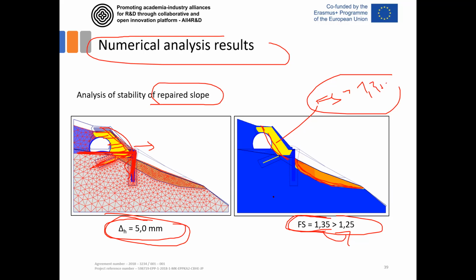As you can see, in this calculation, an additional conservative measure was to remove all this material here. That's actually a possible scenario in the real world, since the stability of this dump material is not appropriate. The safety factor of this remains in the range of 1.0.